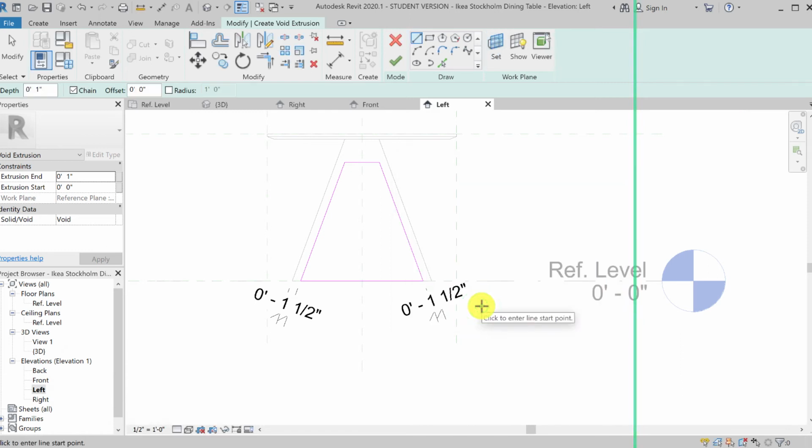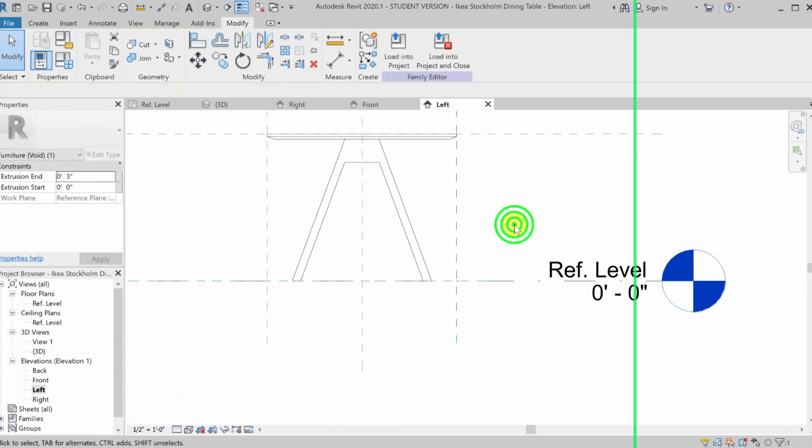Okay, and I want the thickness of this to be 3 inches, and I get this wrong all the time, but sometimes it'll be placed toward the left of the plane, sometimes it'll be placed toward the right of the plane, but it's no big deal. If I get it wrong, I can always come back and add a negative value to it. So I'm going to confirm that I'm done with this geometry. It looks like it's creating that cut for me, so the positive value works.